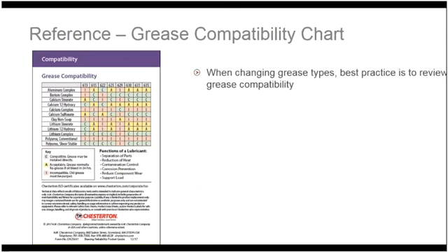And lastly, but certainly not the least important, is grease compatibility. As you can well imagine, there are often other greases that are in the bearing, and there is some concern over grease compatibility. What we have done with our greases is to do the necessary testing, and we have produced the chart on the back page, which indicates the level of compatibility for our greases based upon other grease thickener types.